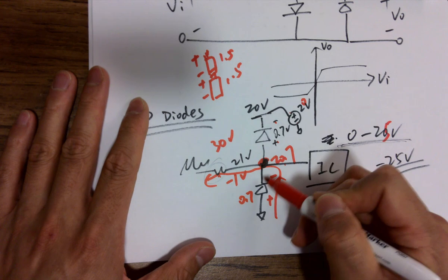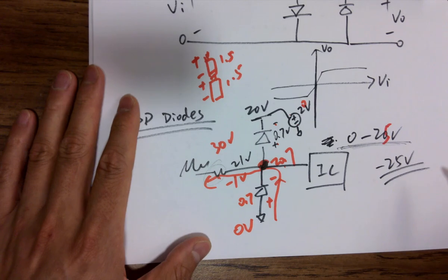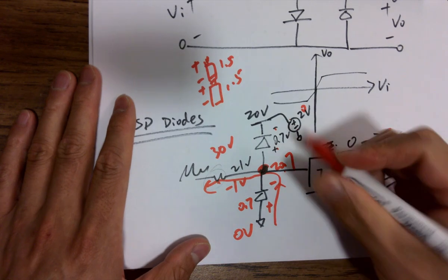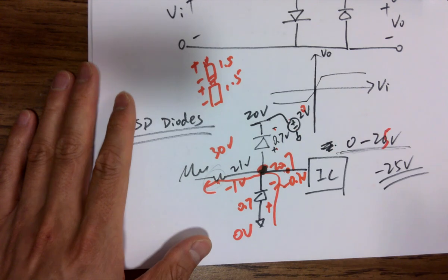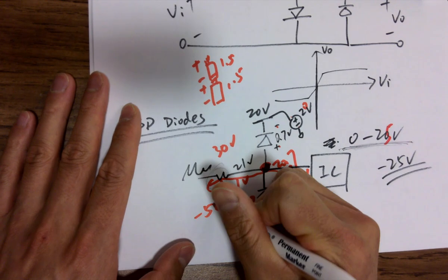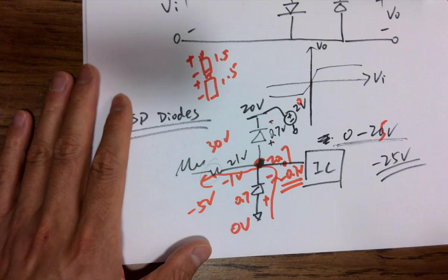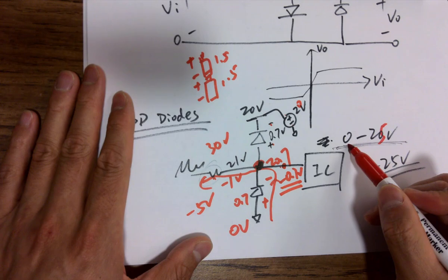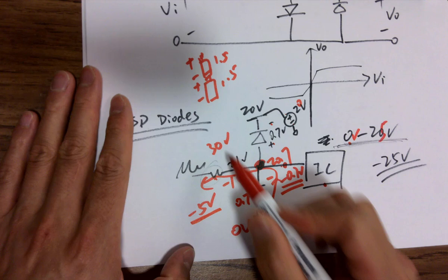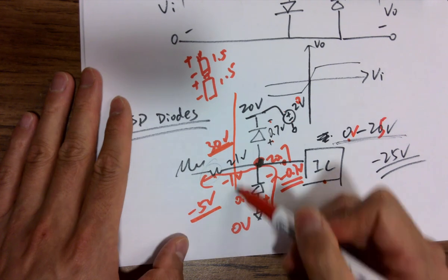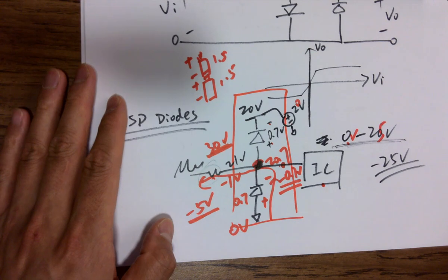it's a 0.7 volts drop permanently, okay? Because you know this is 0 volts for sure, and 0 minus 0.7 ends up with what? Negative 0.7 volts, and it's being clamped. Even though you have like a negative 5 volts surge, it'll keep this voltage at negative 0.7. It's not too bad at all. It's still very close to 0 volts, so you can protect this one from being damaged by that surge. Okay. So that is why all the integrated circuit pads need these ESD protection diodes in them.